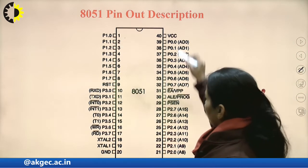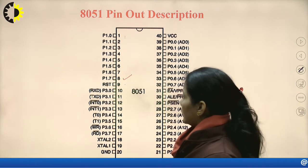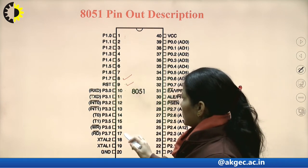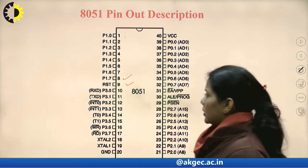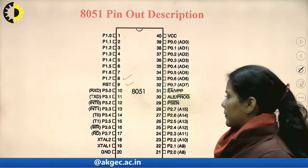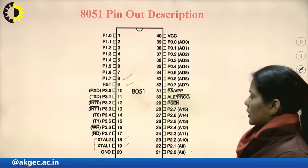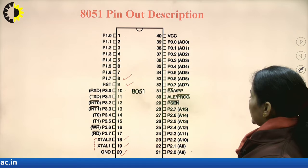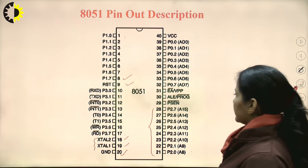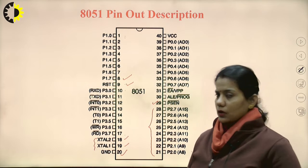From pin number 1 to pin 40, pin number 1 to 8 represents port 1. Then pin number 9 is RST. Pin number 10 to pin number 17 represents port 3, having multiple functions as well as simple input-output pins. 18 and 19 represent the connection of the crystal oscillator. Pin number 20 is the ground. Pin number 21 to 28 represents port 2. Pin number 29 is PSEN, that is program store enable.